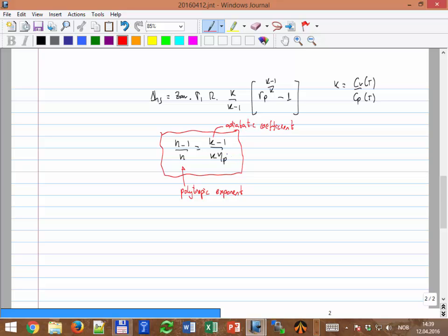And then we have the polytropic efficiency, the value that we wanted, something that is between 0 and 1. So it's very similar to the isentropic or adiabatic efficiency, but now we found a way to still use n and still use an efficiency that is going to have a performance similar to what we observed in the pump. That's the usefulness of having this expression.